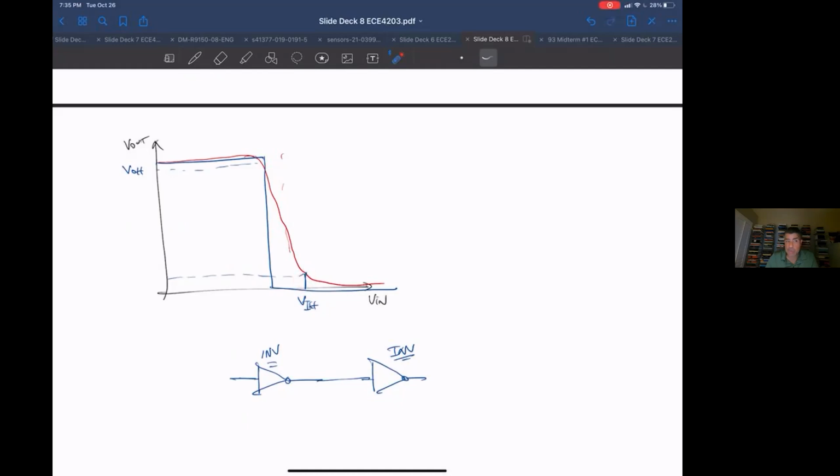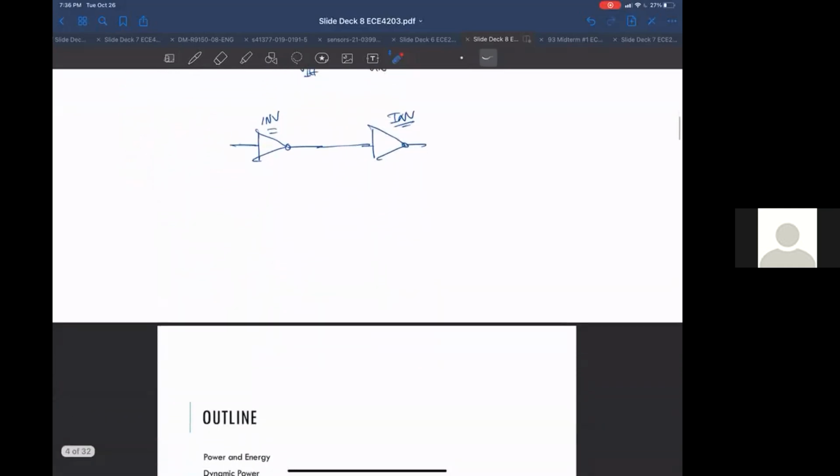So that's noise margin high, and the same thing is true for noise margin low. You have to think about this output going to this input, for a 1 and for a 0. The noise margin is what's the worst case 0 output I have here compared to the worst case 0 input I accept as a 0 here without messing up the communication. Does that make sense? I don't know if I'm just confusing you guys more, but any questions about that? No? Okay. Not so far. Okay, so we'll just leave it at that.